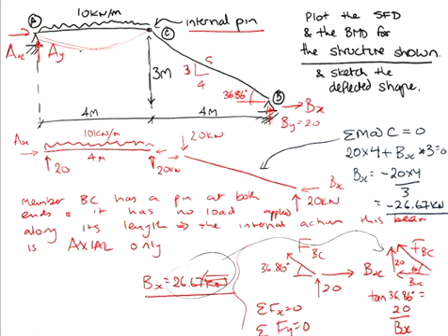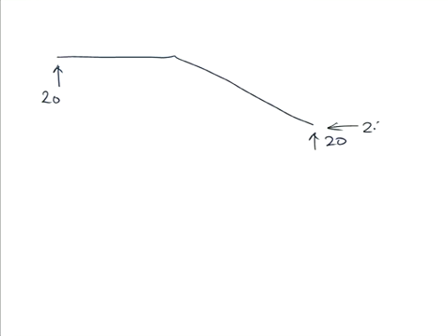As drawn here, our horizontal member will deflect down. Member BC won't experience any bending, it will shorten, but you can't see that in this deflected shape. Okay, so now we draw the shear force diagram. So what did we say our reactions were? We said that's 20, that's 20. I worked out that that was 26.67, so therefore my reaction at A is also 26.67.